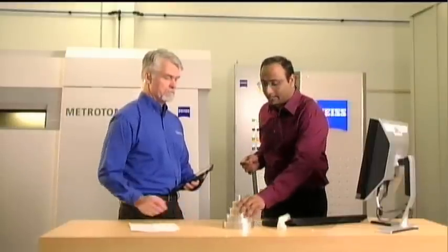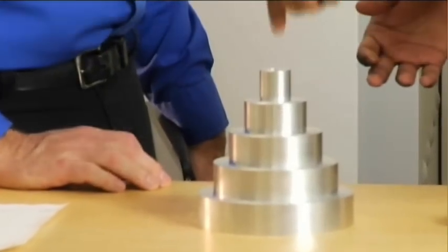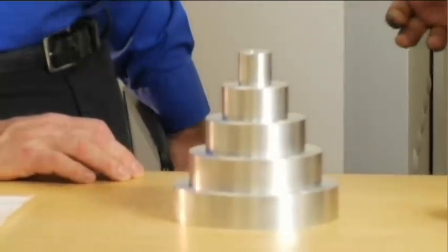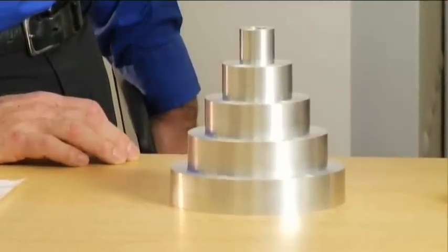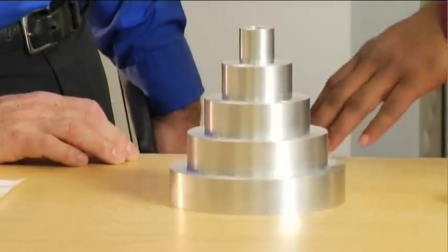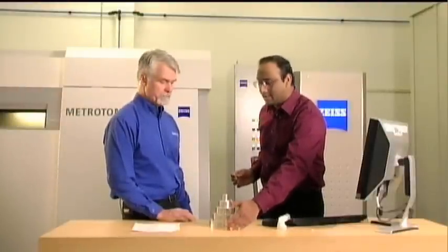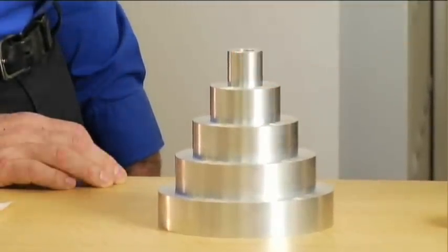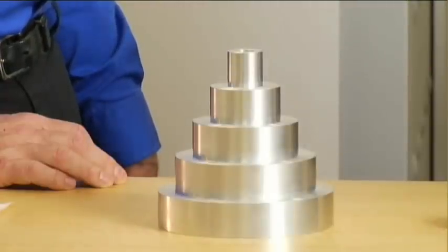If you look at this artifact, it's a stepped cylinder artifact. I have a hole that goes all the way down into the part, so the inner diameter of that hole would not change even though I have varying material thicknesses. But X-rays look at it slightly differently. As X-rays go through the thickest layer at the bottom, they have a different signal on the detector. At the top, there is less material, so I have a different signal. Even though the material is of the same density, based on the path length, I have different intensities that are collected on the detector.